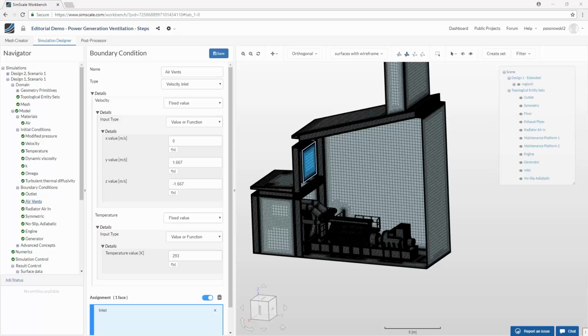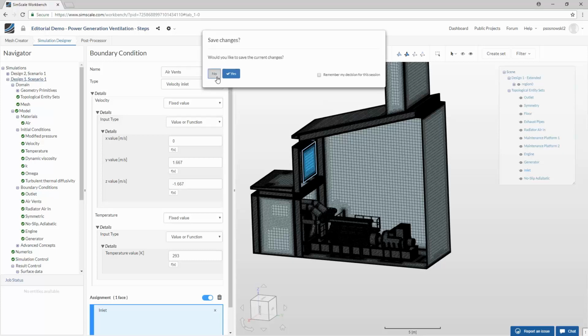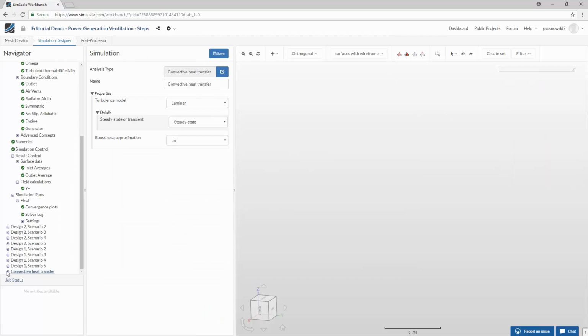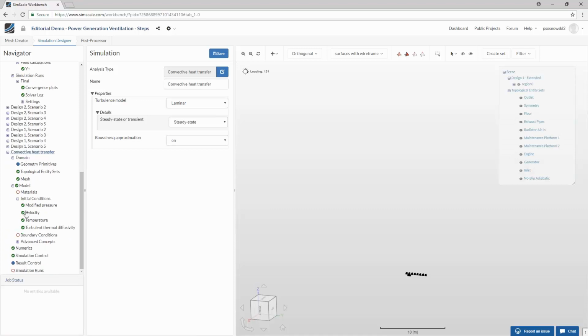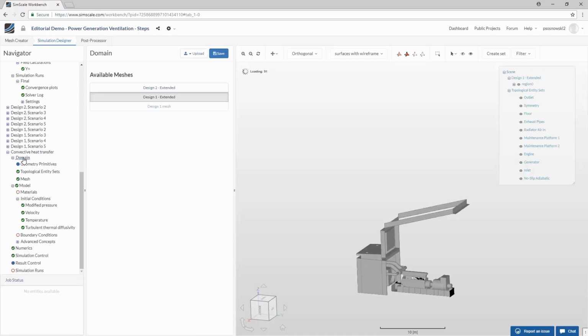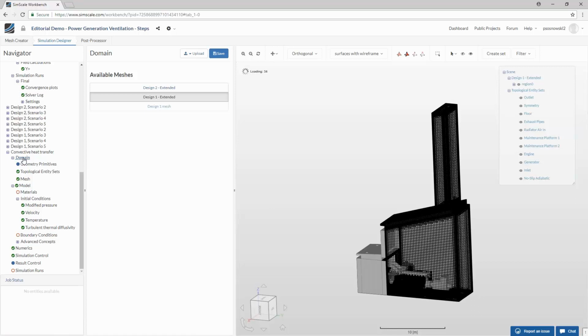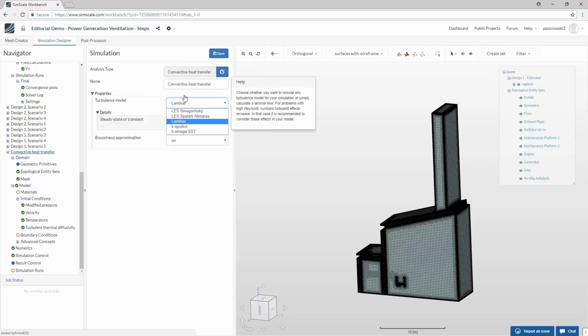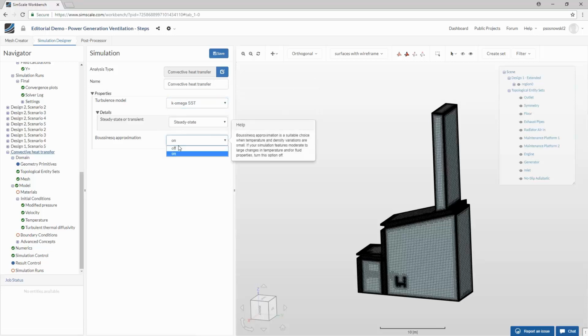Okay, which turbulence model should be used depending on various models? This is a very good question, since we have multiple turbulence models available. So let's jump to the project. If you know that your flow is not subject to turbulence, that is, the Reynolds number is below the threshold for the flow conditions, you would go with a laminar flow. That's pretty obvious. Then most of the time I would encourage you to use K omega SST model, which in a way became a standard for the industry itself.